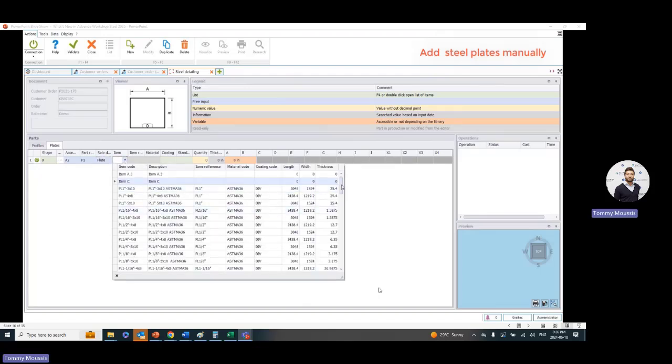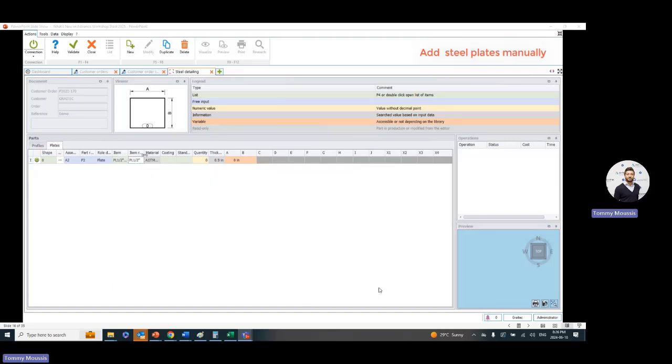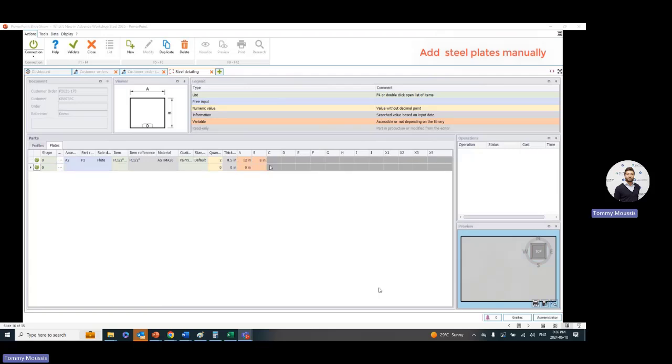So here, once the plate is selected, you would then apply your part mark information. So, of course, the assembly mark and attached part mark, you would define the role of the item and then select the item code for material consumption. And then here you would select your material grade, coding, and quantity count. Depending on the topology selected, it will then activate the cells necessary to modify the dimensions.